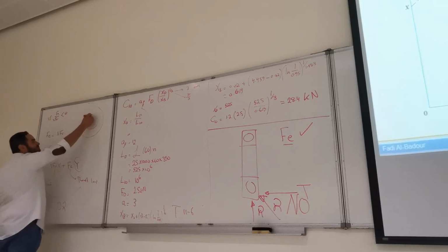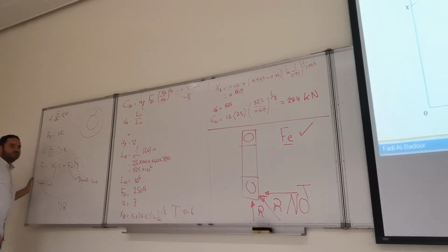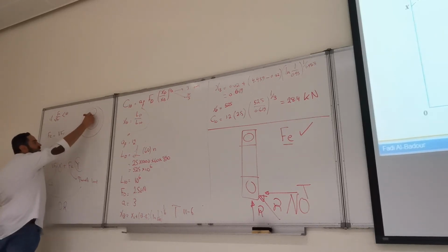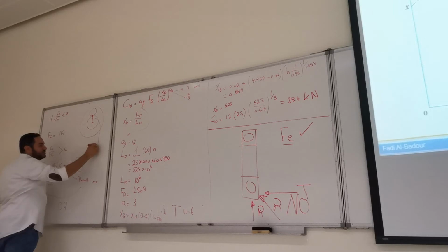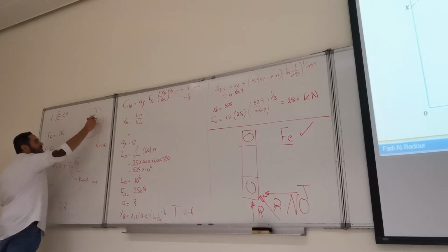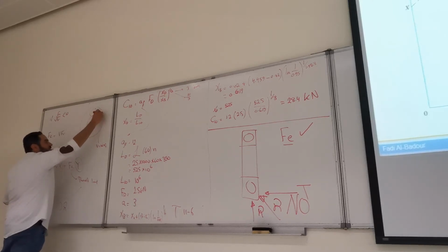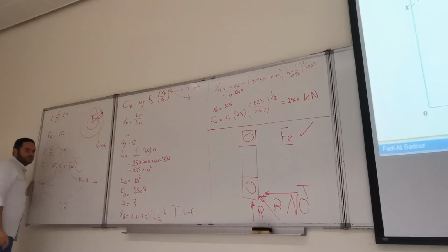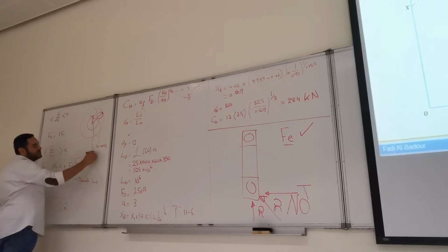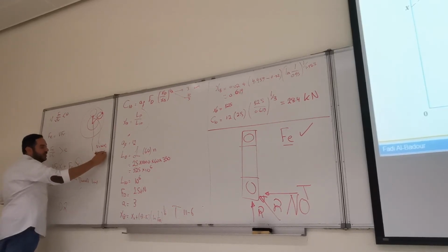Velocity. Now this is your roller. This is the center of the bearing. If the inner ring is rotating, what is the velocity here? It is V equal to omega times R, let's call it Ri. So what if the outer ring is rotating? What is the velocity here? It is simply V equals omega R outer.